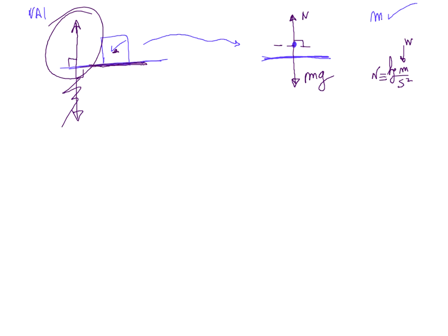Third step. What is the third step that we need to do? Excellent. Free body diagram. The free body diagram had 3 components to it. Could you remind me of those 3 components? Essential components. A free body diagram needs to include all the external forces, excellent, with labels. That's 1. There's 2 more. A coordinate system, excellent. And the third piece that most people like to skip, excellent, the direction of each of those forces with respect to either our X or our Y axis.